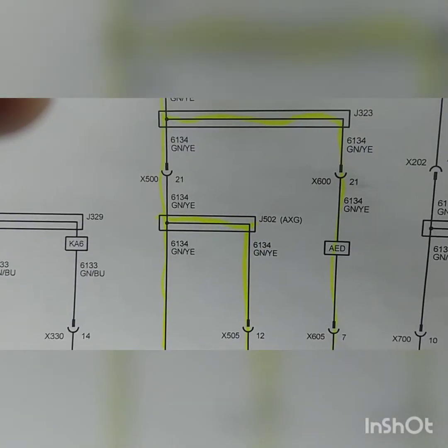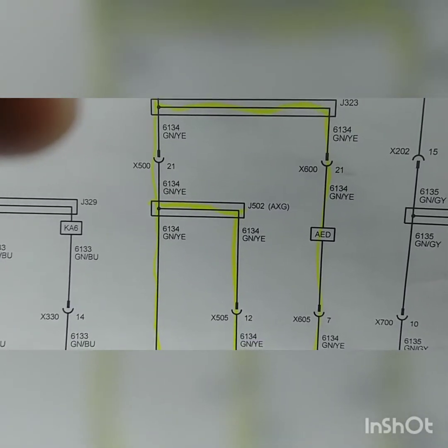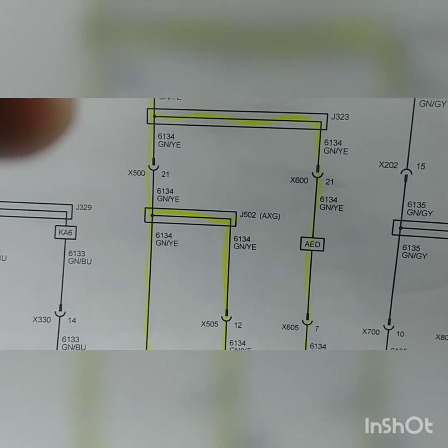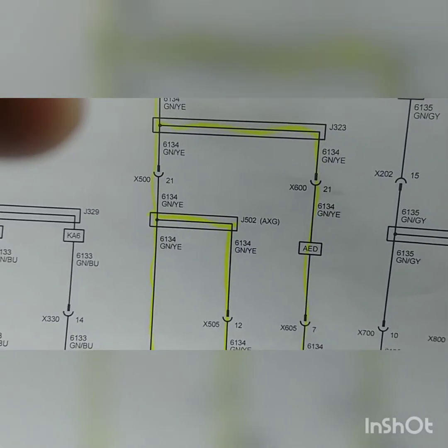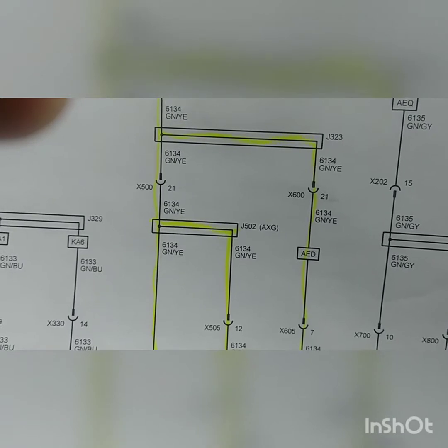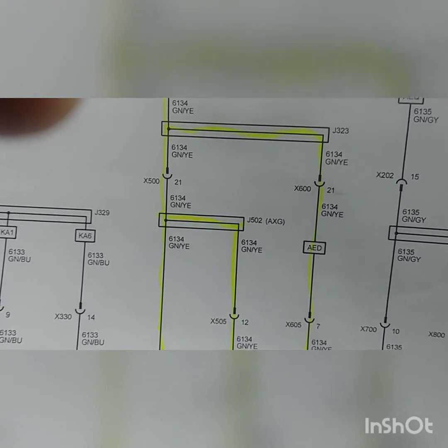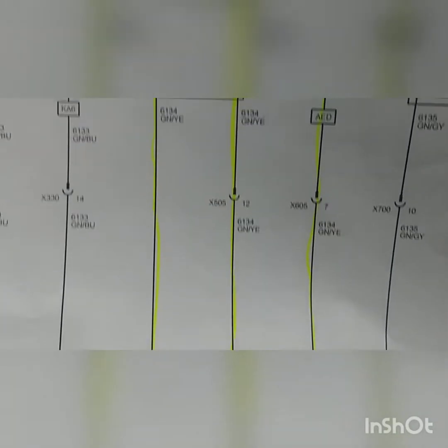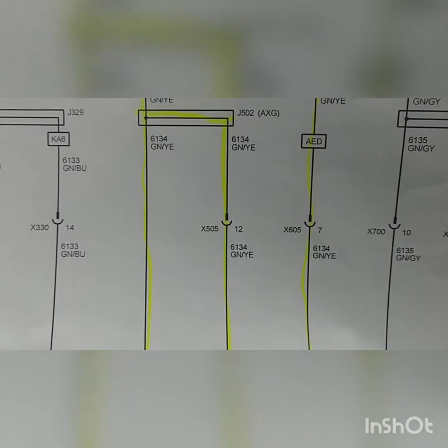So it started getting really noisy at work, so I took it outside. I'm in my car and I wanted to finish up this video. So we reconnected connector 600. We went back to 0 volts. Keep in mind we still have the K9 connector on the body control module, pin 10. We're still back probing that. We're still getting 0 volts when we reconnect connector 600. We move on to connector 605, disconnect that, check the voltage. Now we're getting 12 volts again.